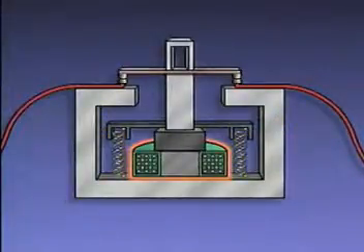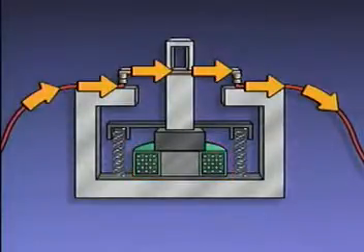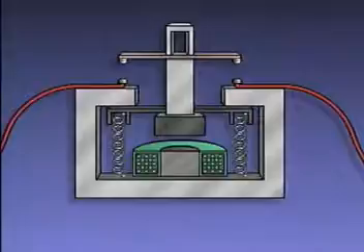When the contacts close, a complete path for current flow is established through the controller to the motor. When the M-coil is de-energized, the electromagnetic field is removed, and the springs push the armature back to its original position, separating the two contacts.